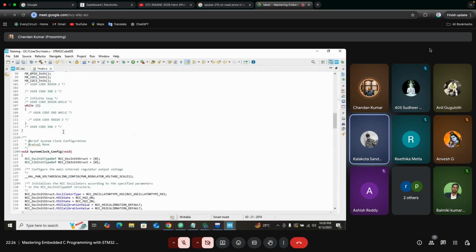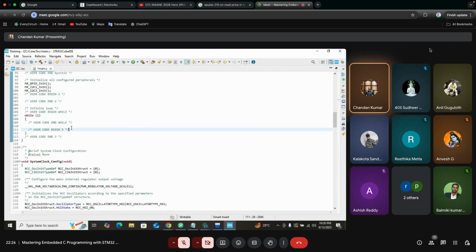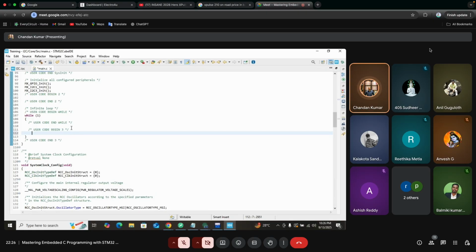So we will use while(1), because my master will transmit continuously, and once the slave receives it, the transmission will stop. If my master does not want it, he will keep sending. So here we will use HAL I2C, and we are transmitting as a master.